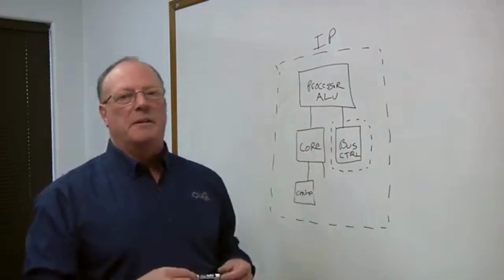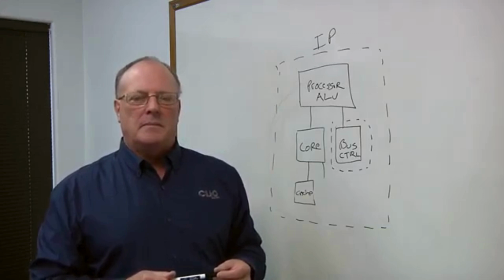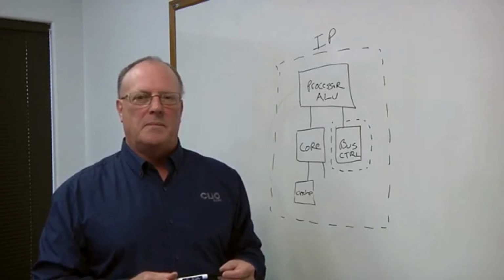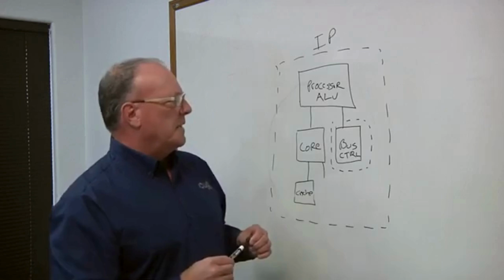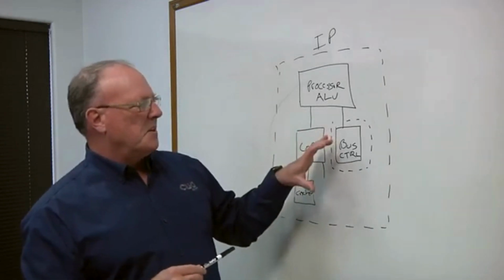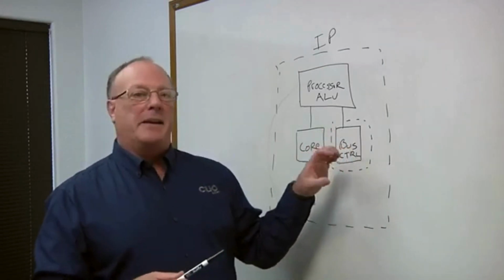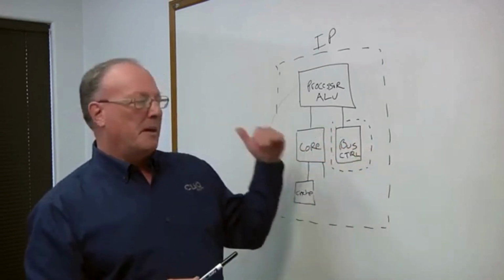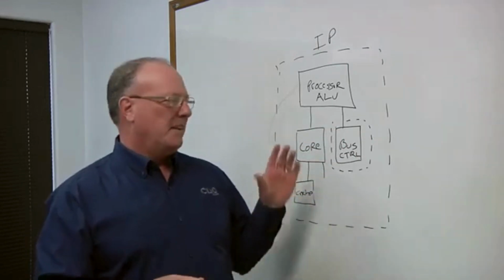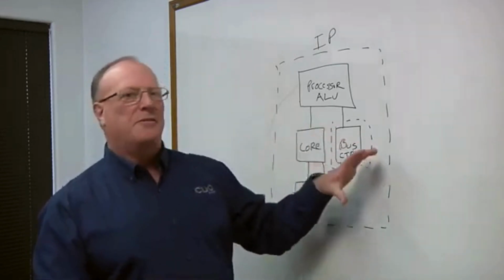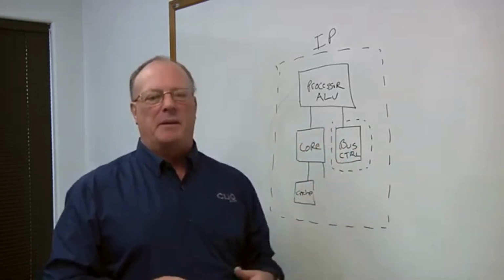And knowing specifically what versions you're using within that bill of materials is also very important. As you change out the IP, that also has an effect in terms of other things that are in that chip too, right? So now you have to go back and revalidate everything that it works with everything else. You do, and that's part of having a bill of materials and knowing, particularly when you get into functional safety, if I swap out that IP, all of the validation that I did to make sure that my functional requirements are indeed met has to be redone. So you have to make sure that, when you swap it out, what tests are affected and what specifications are now invalidated because I swapped out that IP.